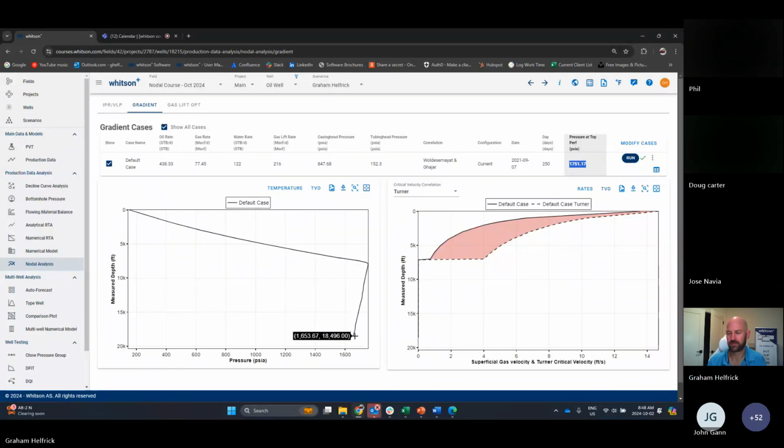Because it's a toe up well. Exactly. This is a toe up well. And so the pressure here at the toe is this pressure here. And then as we go to the heel, there's a vertical drop. So there's gravity happening. That's why the heel, right here, has the highest pressure. If you ever see a weird looking shape like this, that's just why, right? We're toe up.